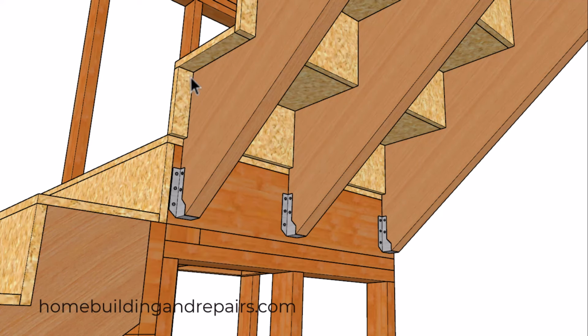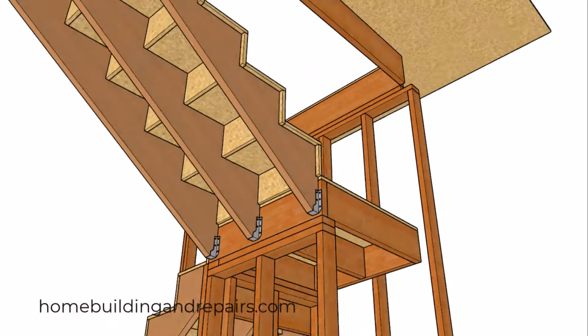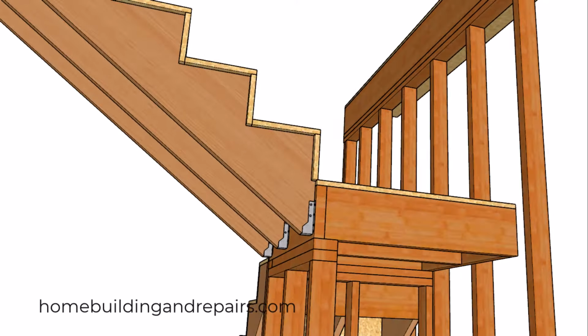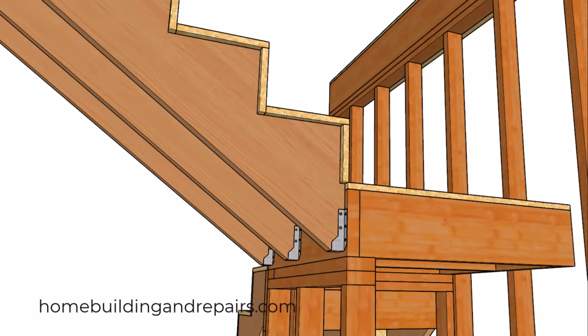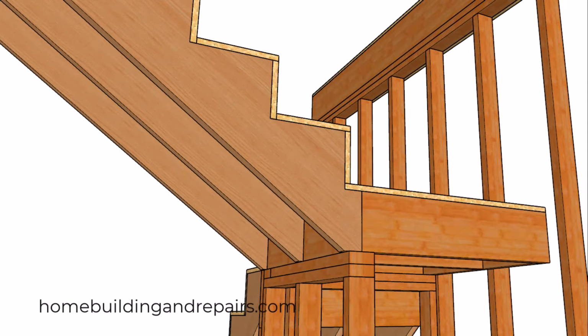And sometimes the triangles that you cut out of the stringers when you're notching them can be used to fill this area in here, and then just run a 2x4 or a shaped board along this edge here. And of course you can always get as creative as you want to there. The principle should still be the same. The hangers should work. However, if you don't like that idea, then we can go ahead and try this.